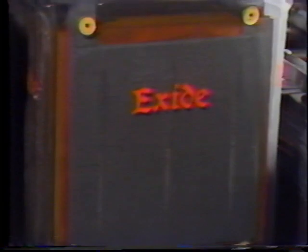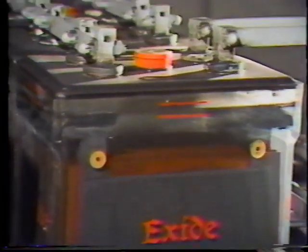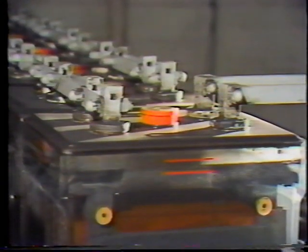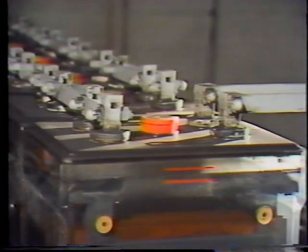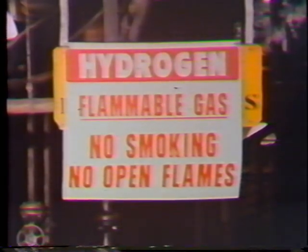As this other cell is being charged, the water in it breaks down, and two gases are given off, hydrogen and oxygen. The gases bubble up through the electrolyte as the water changes to sulfuric acid, and they escape from the cell through vent holes like the one we saw earlier. The escaping hydrogen gas can be extremely dangerous as it mixes with air. As little as 8% hydrogen in the air can be an explosive mixture.